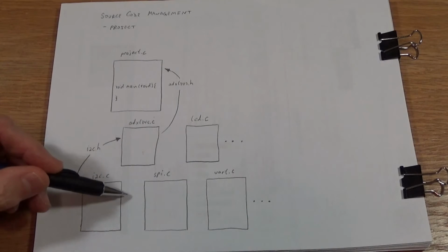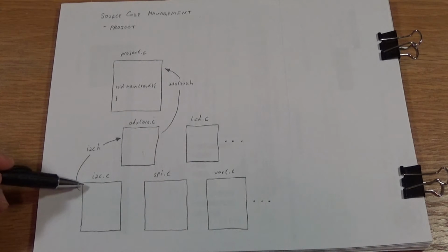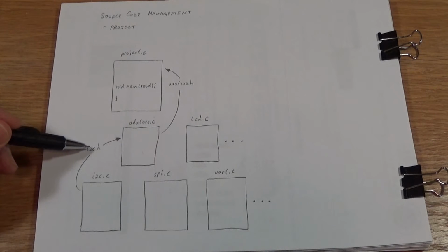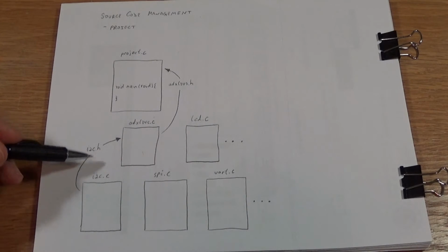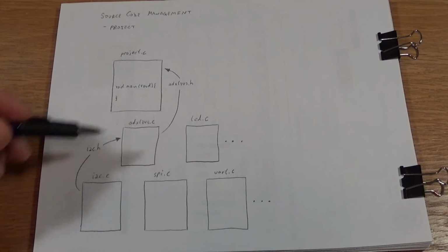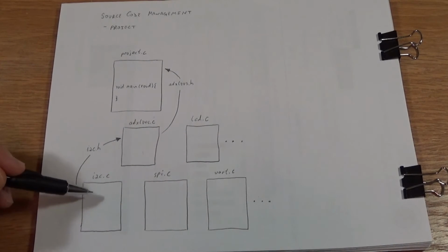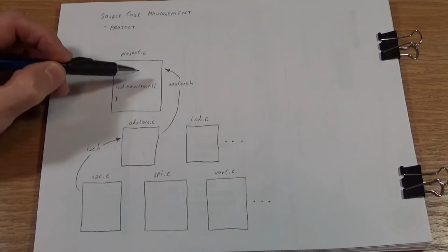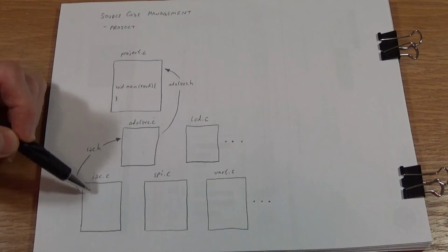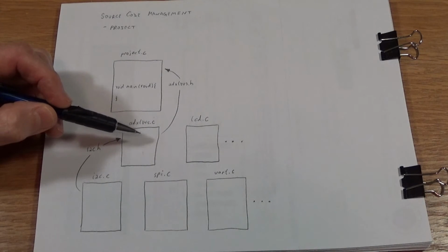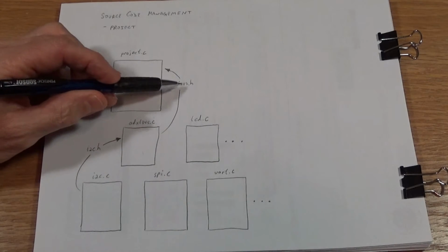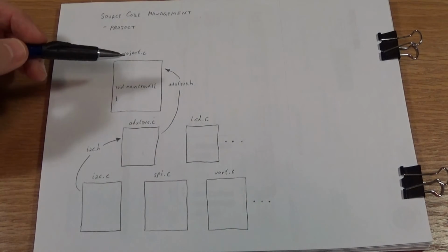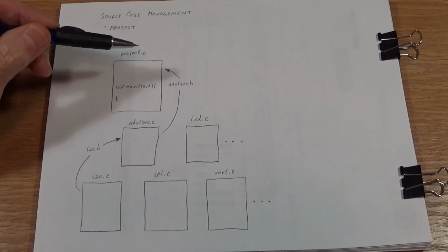And so when you've created this driver for the I2C, you'll create another file called the .h, or the header file, the include file, which tells this and everybody else outside of this module what's going on in here. It's the interface, the public interface. And the same with your project. The project needs to know about this guy, but it doesn't need to know about I2C. So you only need to include the header file for this one, the .h file.